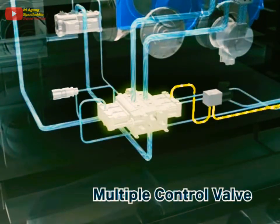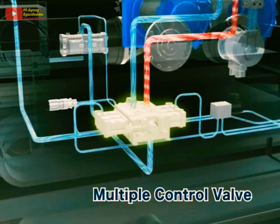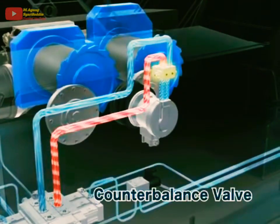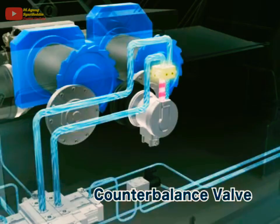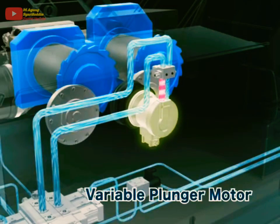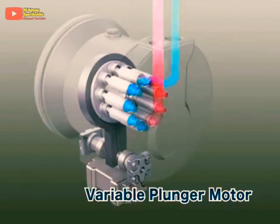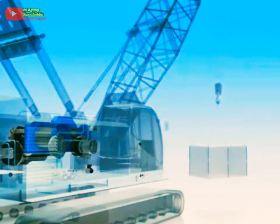Hydraulic oil from the remote control valve's outlet port is sent to a connecting pilot port of the multiple control valve, which then moves the spool. Based on the position of the spool, an outlet port is selected, and oil is then sent to the variable motor's counterbalance valve. Hydraulic oil passes through the counterbalance valve and heads towards the variable motor, where its pressure then rotates the motor. The drum rotates along with the motor, hoisting or lowering the load.